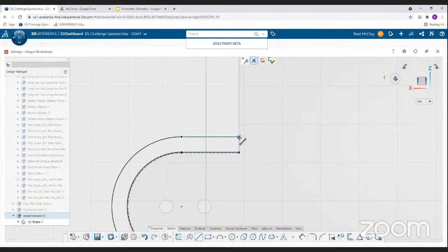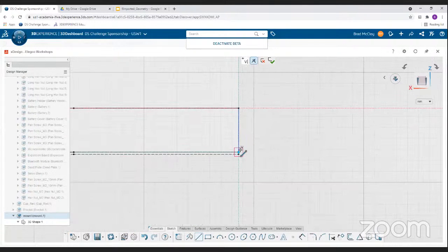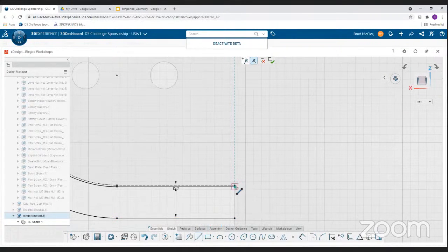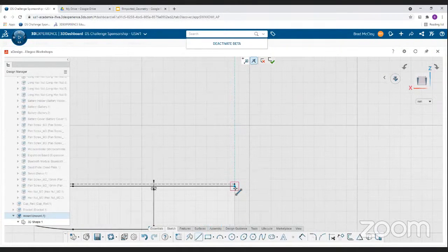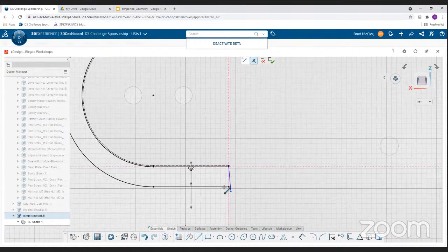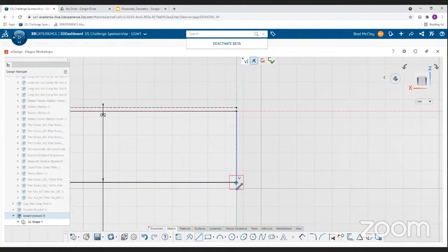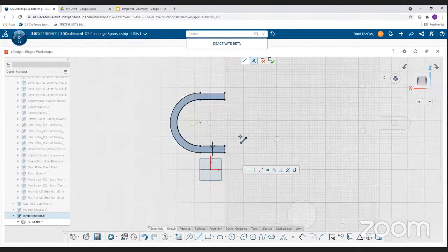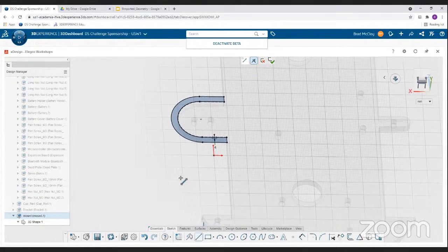So we take a line. If you don't quite know what we're trying to do yet, you'll get it soon enough. I'm going to zoom in. We'll close the other side now. And this is why zooming in is really important. You can see how I was kind of picking the wrong point there. I was picking a construction line. There. Now you can see that colored in. So if we were going to have this kind of cup around that new mounting flange, that would be good.